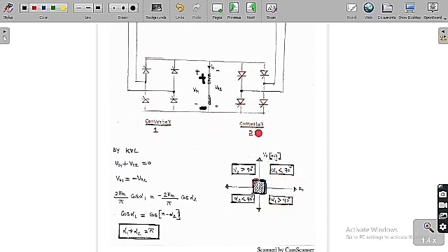But because of the second converter, when alpha 2 is less than 90, this plus or minus V naught is always positive. If this is positive, it means V naught is negative. So therefore V naught is negative, so this is negative V naught. And also the current in this case is again negative. So we are going to get this third coordinate.